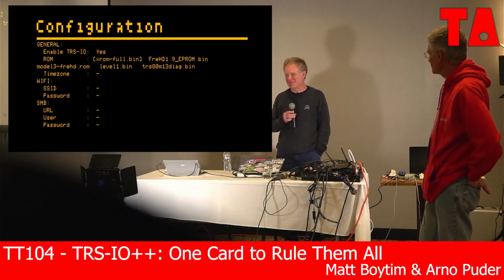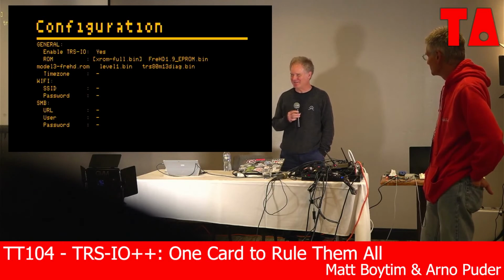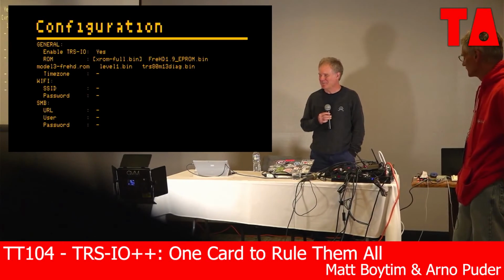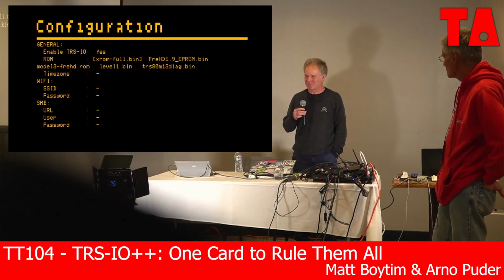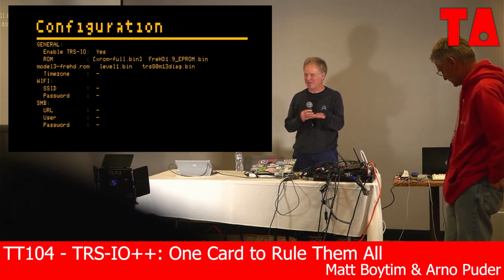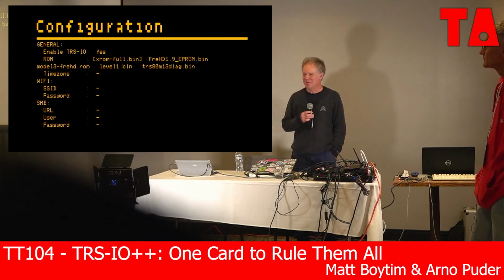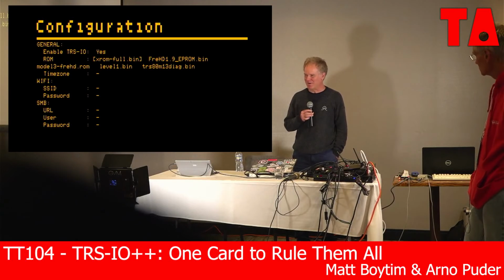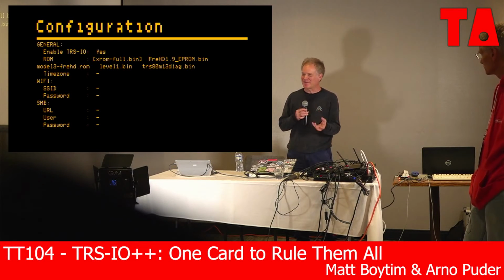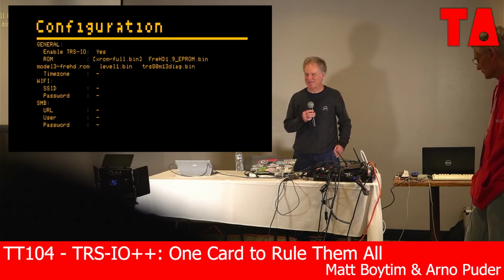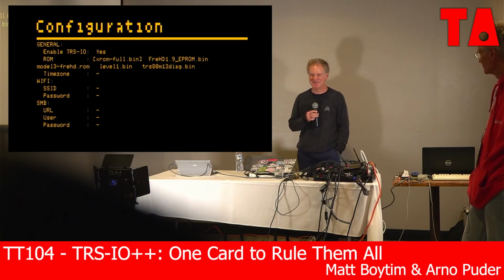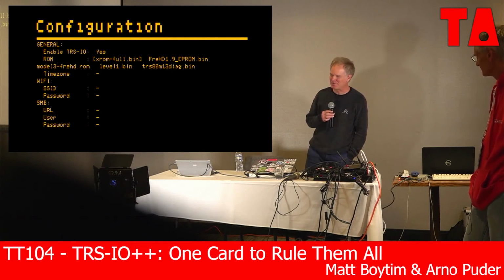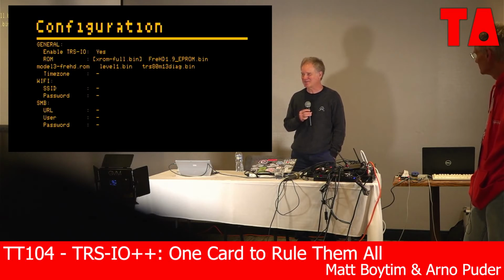That might be a limited edition, but the DDR3 connector, that's a bitch. Yeah, I mean, we have actually played with some techniques on using PCB stencils to apply solder paste in a reflow oven. Sasha actually printed a little negative pressure box that can pull the PCB stencil down, and I hope that I have a bit more success. Like I said, I ruined 3 boards trying to hand solder it, and I cannot do it without a reflow oven. So there might be a few boards at some point, but don't hold your breath.